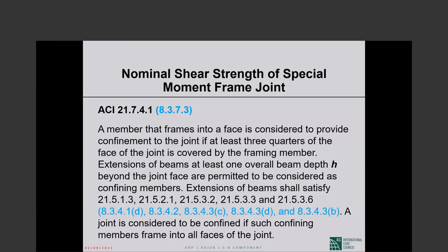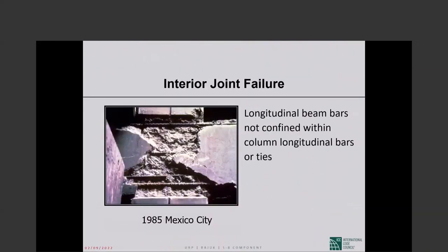Okay, so that is, and most people I know, they do not vary the spacing of the transverse reinforcement. They drop the sum of the cross ties, making concrete placement within the joint much easier. Okay. So that is a detail. I'm not sure I put it on the slide, but that is kind of important.